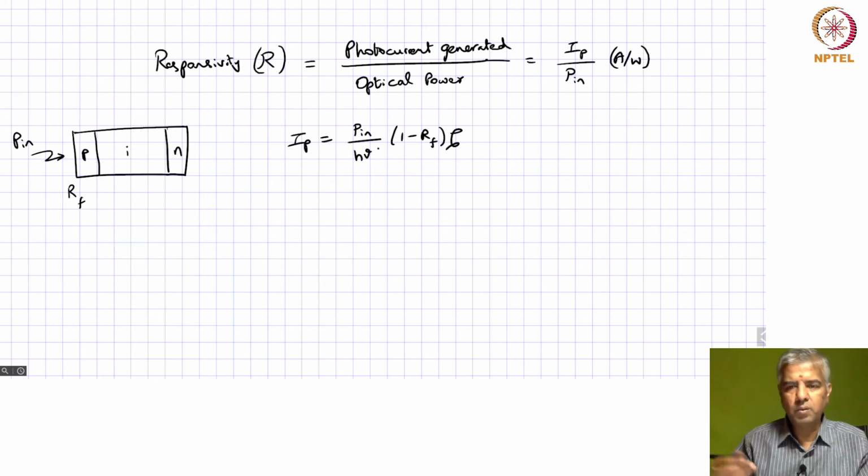So now I'm starting to talk about charges, so I'll have to multiply this by Q. Then that's the electric charge, and it corresponds to the number of photons that are absorbed within the structure. When you look at absorption happening within that structure, it tends to go as an exponential. Why is it an exponential? Because it conforms to what's called Beer's law.